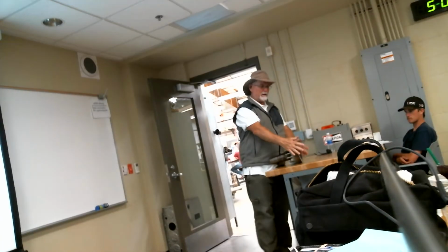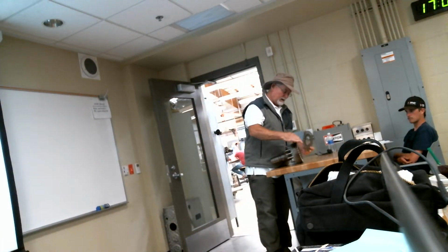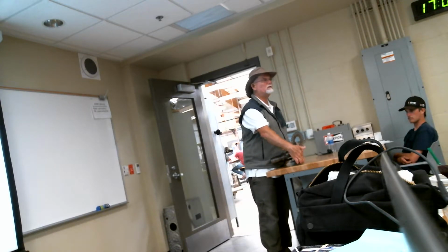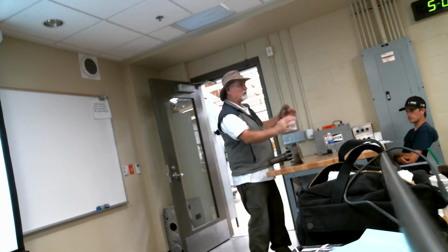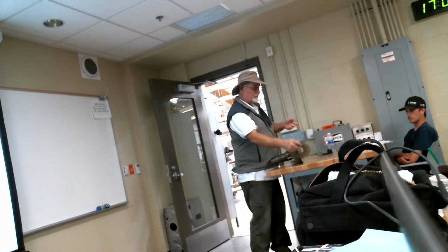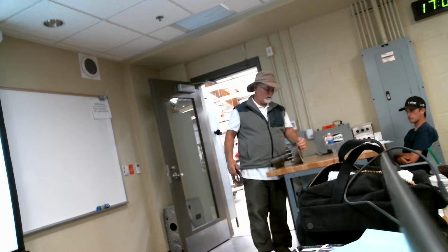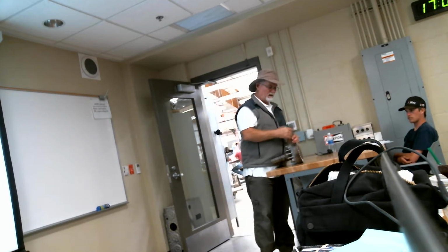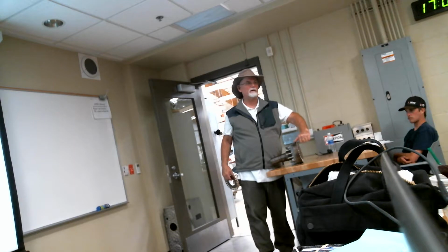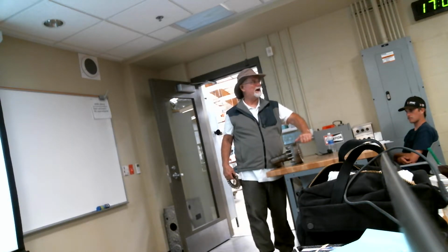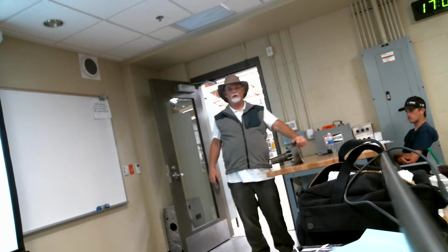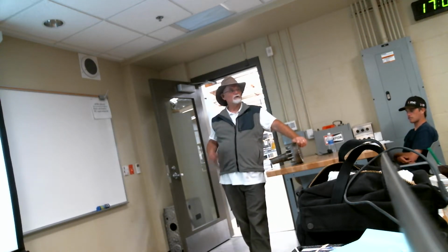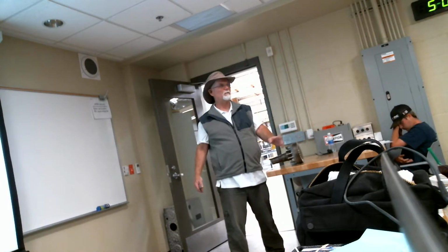So note a bunch of laminate plates in here. Each one of these big aluminum bars, the magnetic fields are going to be cutting through at right angles to these big aluminum bars. So in these bars, current is going to develop because the magnetic fields are cutting them. As current starts to develop, you're going to get magnetic fields running this direction, which are now at right angles to the magnetic fields inducing the original current. So just like we said in the DC motor, one side's going to push, the other side's going to pull.